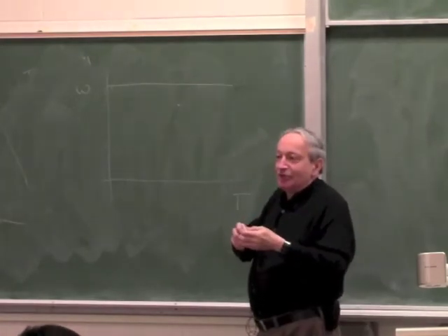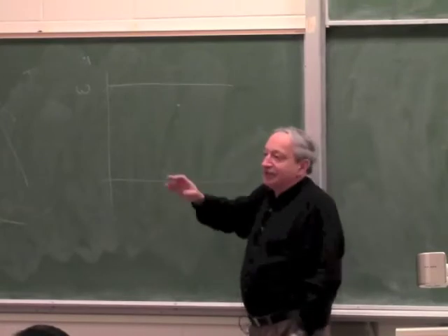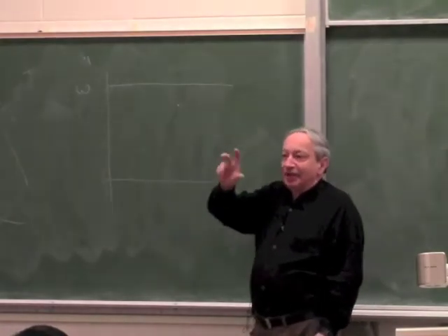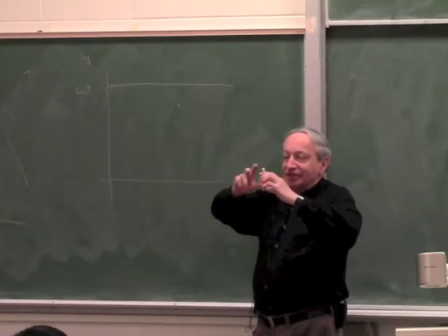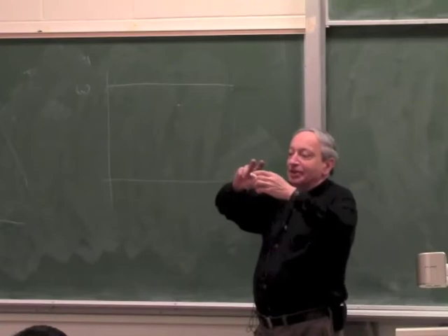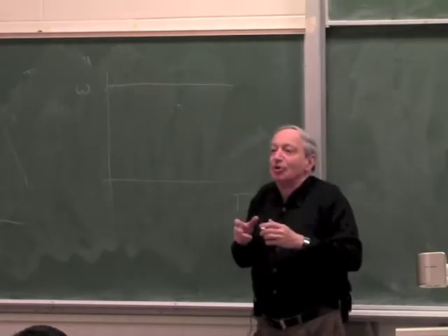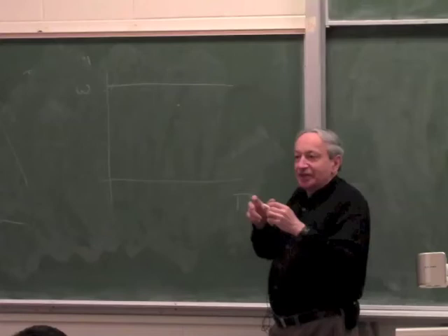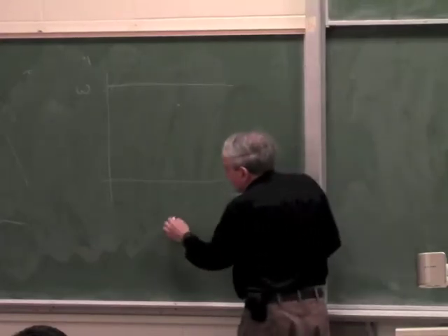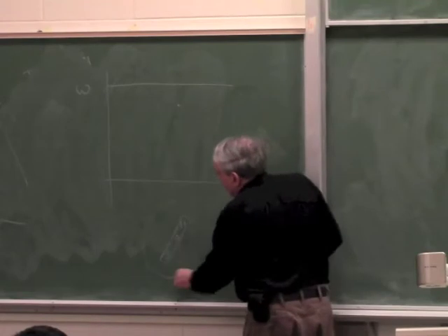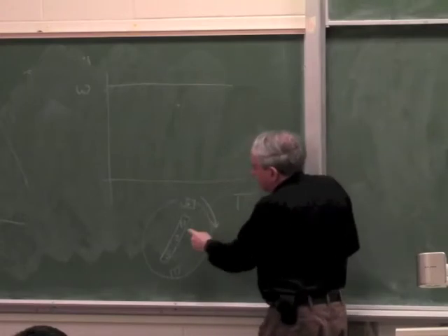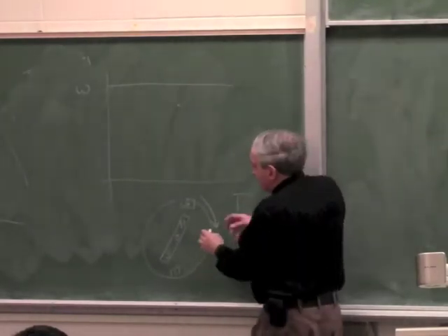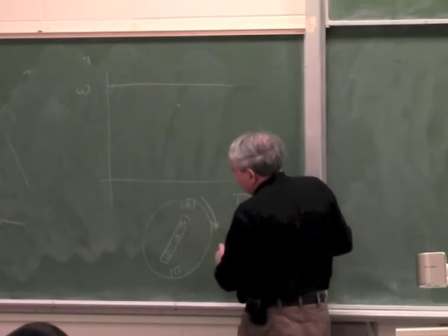It can't follow anymore, because remember, the rotating field creates the equivalent of a rotating magnet. The armature is another magnet, and the one magnet follows the other. But at some point, there is so much torque, the magnet can't follow, because the torque is more than the torque the two magnets can generate. Remember the analogy. You have a rotating magnet NS, and the rotating field looks like a ring with another two magnets on it, and this ring rotates and this is following, but it starts winding up. As it follows, it starts winding up.